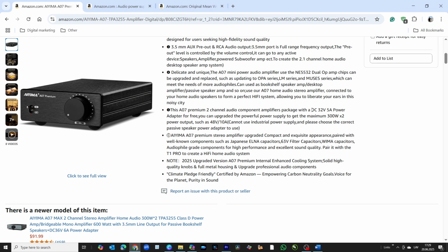If you choose that system, then you should accept that for an 8 ohm load you have 40 watts, and for a 4 ohm load you have 80 watts, and then your system is balanced. And 80 watts of clean power is very good power. You can drive even relatively large floor standing speakers and listen from 2 to 3 meters, and it's more than enough for near-field monitors. So overall it is a balanced system, and it's coming with the right power supply.